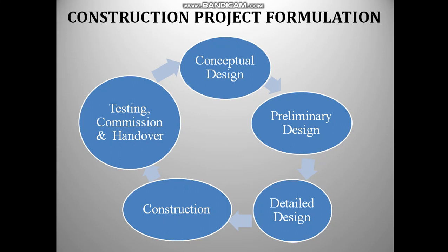How to break down the overall work into small definable work called activities and put them in sequence, which means construction planning. How to calculate the time and resources required to complete the activity and obtain the criticality of the activity, which is nothing but construction scheduling. How to distribute the labor and equipment in order to accomplish the work in the given time, which means labor, equipment and resource allocation. And how to prepare the bill for the money invested in the construction to get the payment from the client, which is construction finance.